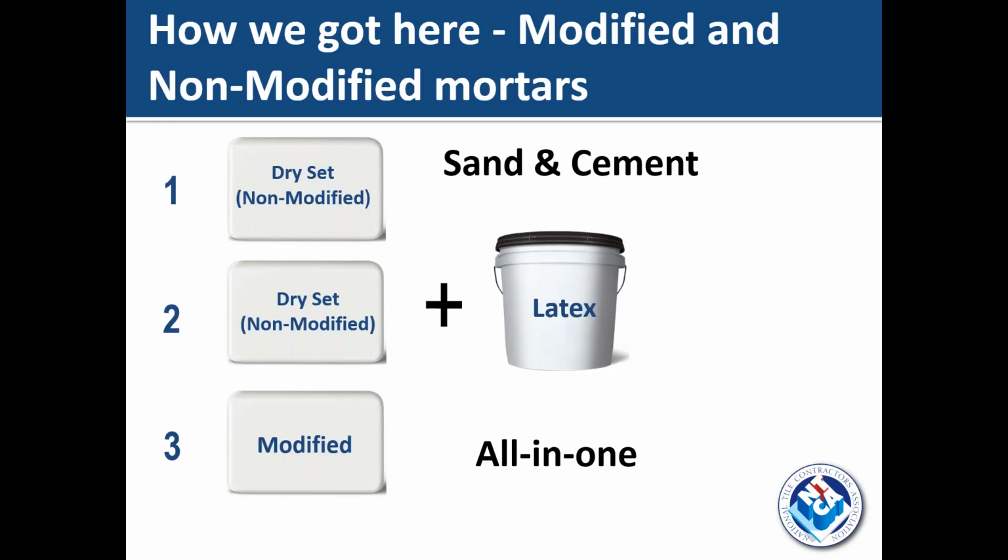So first, I want to talk about modified and non-modified mortars. There has been a progression in the industry with these products, starting out years ago with dry set or non-modified mortars, and then we came to introduce modified mortars, and the first modified mortars were adding a liquid latex. This is about 50 years ago. And now all of our products, or most newer products, are all one product. So the latex is already mixed in with the powder.